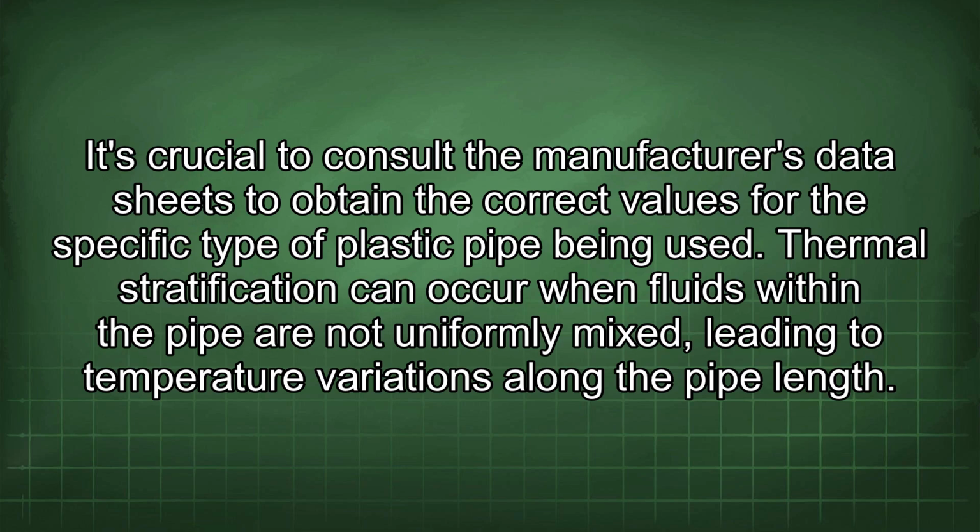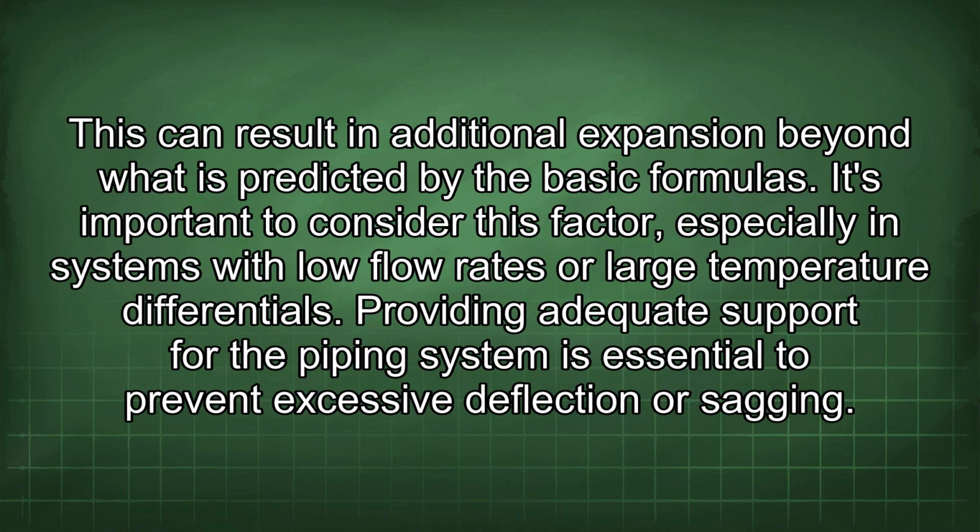Thermal stratification can occur when fluids within the pipe are not uniformly mixed, leading to temperature variations along the pipe length. This can result in additional expansion beyond what is predicted by the basic formulas. It's important to consider this factor, especially in systems with low flow rates or large temperature differentials.